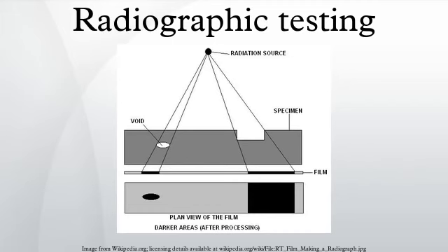Penetrating radiations are those restricted to that part of the electromagnetic spectrum of wavelength less than about 10 nanometers. Inspection of welds, the beam of radiation must be directed to the middle of the section under examination. This can see very different things from X-rays, because neutrons can pass with ease through lead and steel but are stopped by plastics, water and oils.